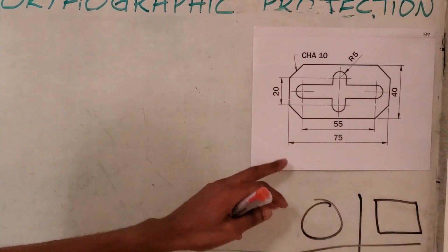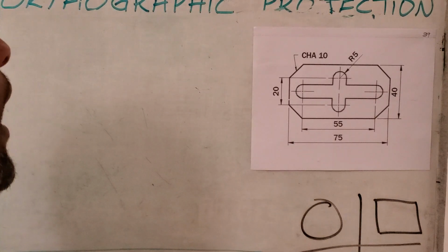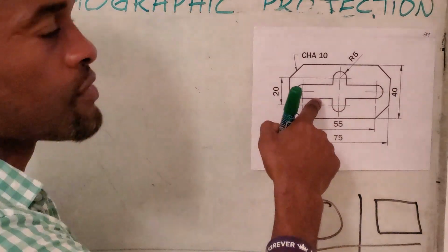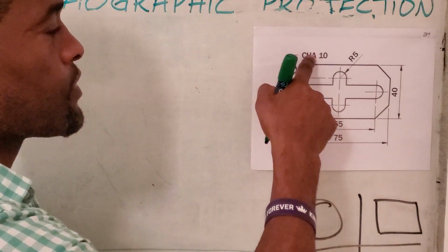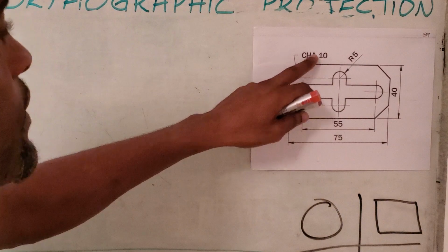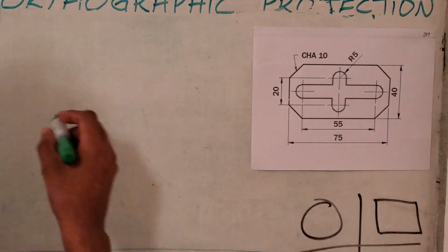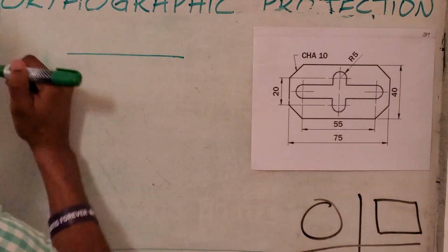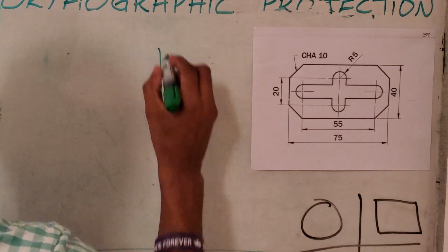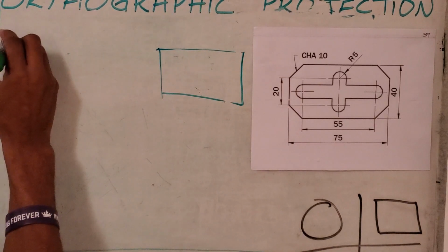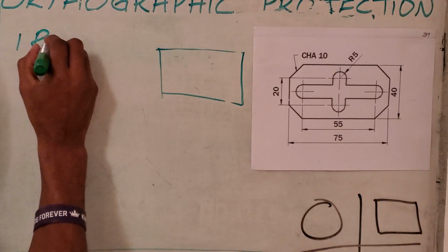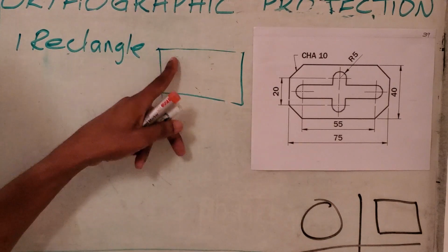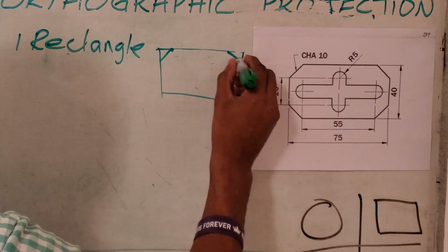So for this, we'll type REC for rectangle, activate rectangle, then click on chamfer, then choose a chamfer of 10. First side chamfer is 10, second 10. Then start your rectangle here. So the first line is rectangle. Rectangle with chamfer would cut off all the ends right here.